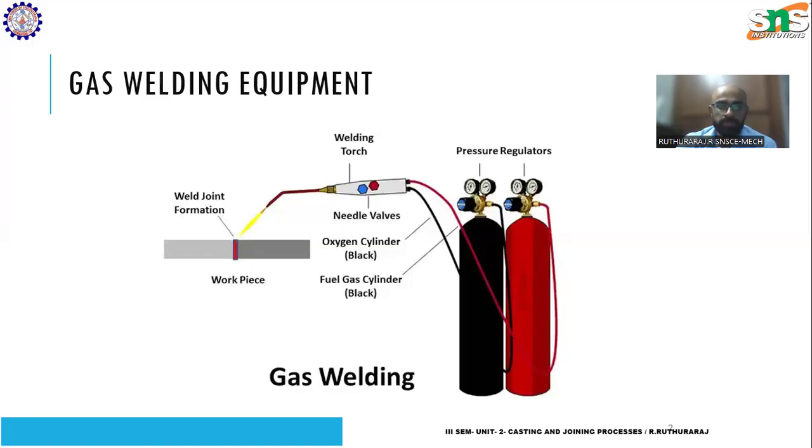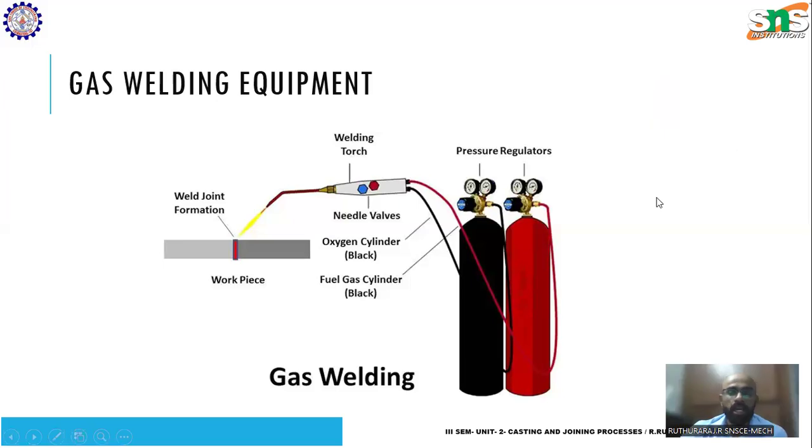As you can see in this figure, both the cylinders have a pressure regulator. The purpose of this pressure regulator is to regulate the volume of gas coming out of the cylinders. Similar to the regulator which is used in your stove, which is just used for opening and closing, here these regulators are used to control the supply of gas coming out. And another function of this pressure regulator, or your LPG regulator, is that it arrests the backflow of air.